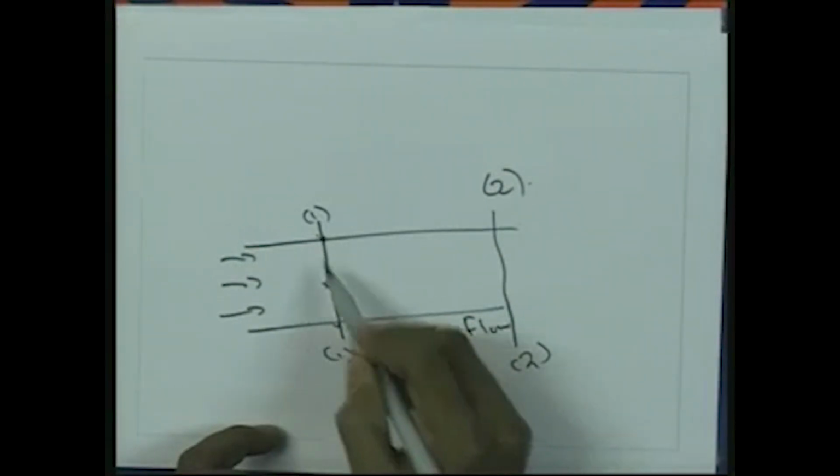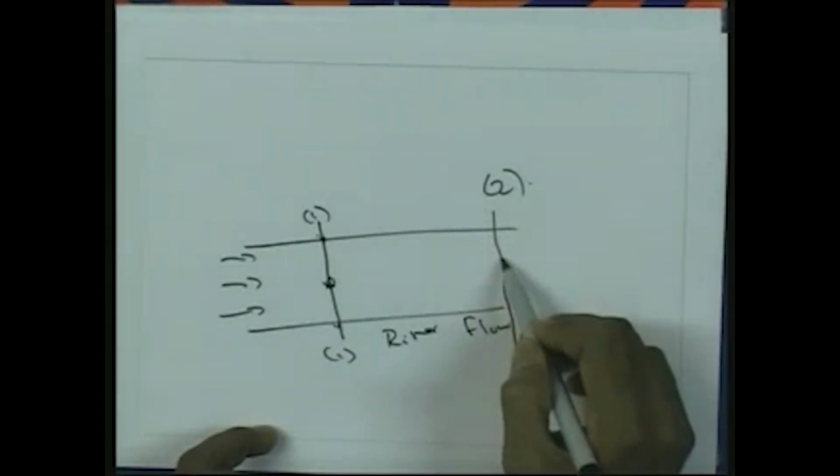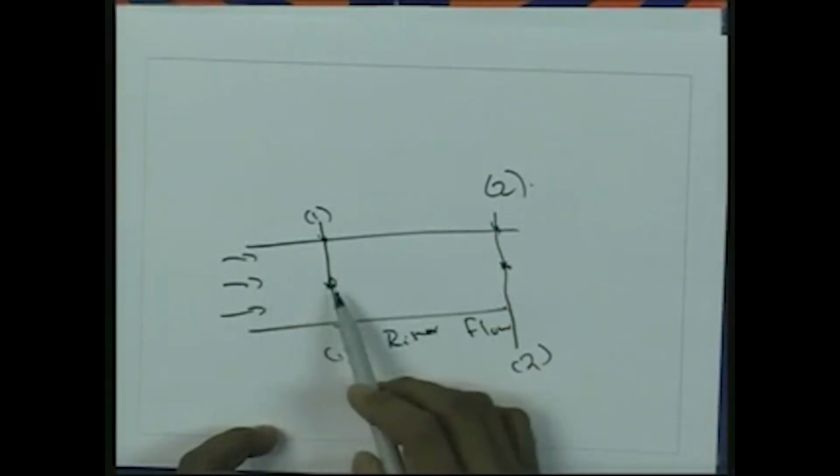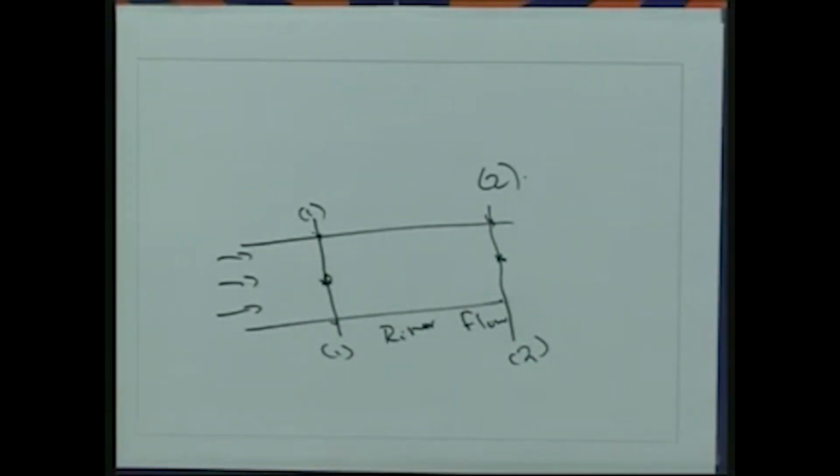Generally, for most fluid flow problems, as we have discussed earlier, we will be using the Eulerian description. From this we get the information, as the flow progresses, in terms of what happens at a fixed point. The fixed point you are considering can be a point or it can be a section like this. With respect to this, we see what happens to the fluid properties when the fluid moves from one section to another, or at that particular section with respect to time. That is the way we will be describing the fluid flow in the Eulerian description.